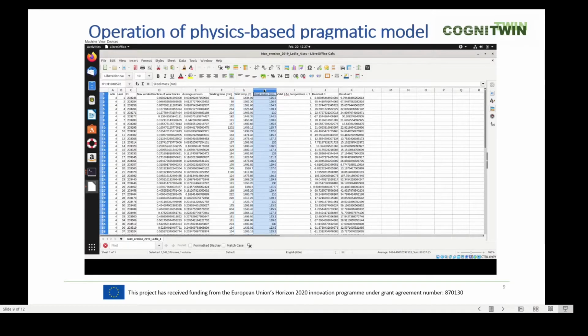Here we have the steel mass in tons. The steel mass is basically a part of the operational data, but it turns out that the steel mass is not the steel that is in the ladle, but the steel that was received by the casting machines. And sometimes there are problems in the casting machine. So we had to make some corrections because sometimes the cast metal was very low, so we have put a limit here of 110 tons.